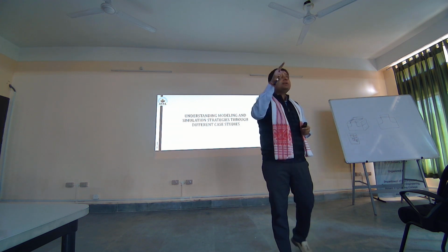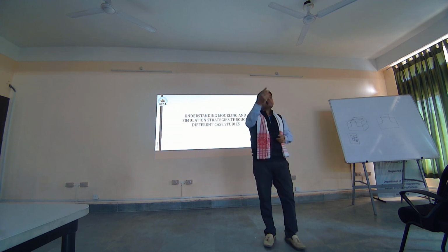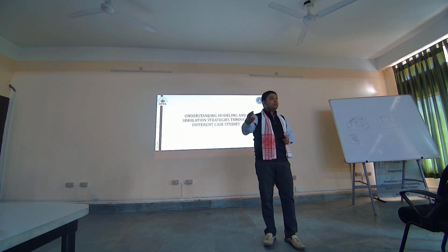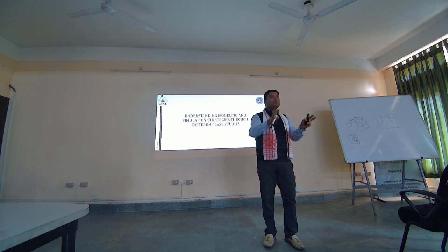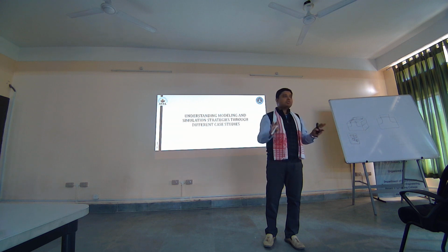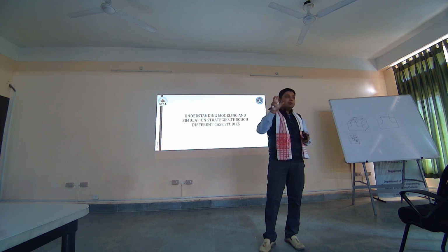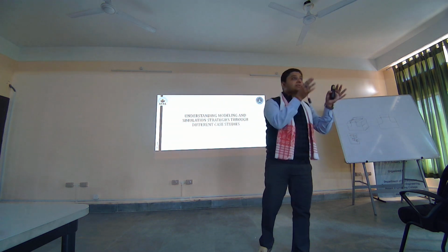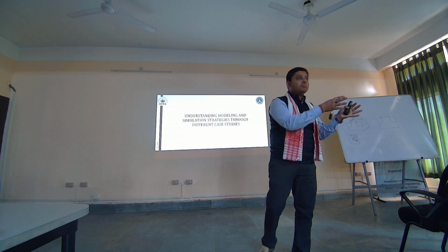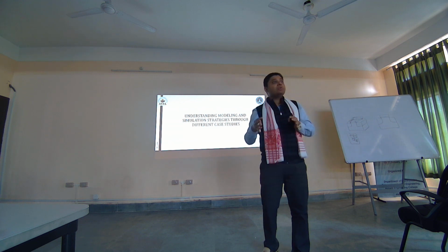So that part you have to understand, because as I have said, you have to know your simulator before doing any simulation. So you have to know your models first. Okay, but to answer your question, one model is never going to do that. It cannot describe a device in its entirety. So mobility will have a different model. Okay, then principle of operation, drift diffusion, hydrodynamic will have a different model. Then band gap narrowing will have a different model.